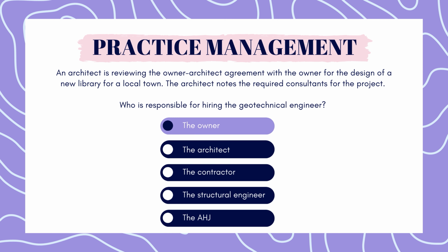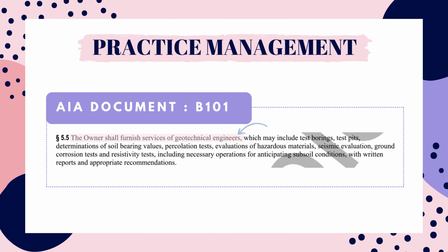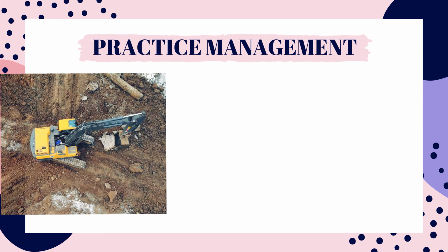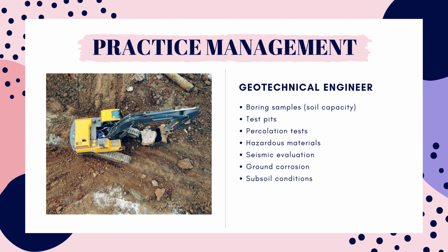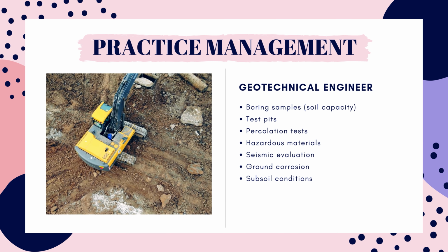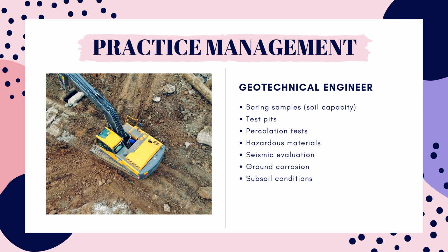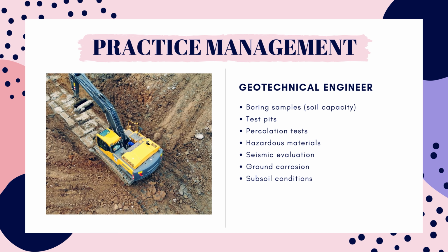The answer is owner. The geotechnical engineer is retained by the owner. This is stated in AIA document B101 under Owner Responsibilities, section 5.5. But what does a geotechnical engineer do? They go to the site to take boring samples that they analyze to provide us designers with the bearing capacity of the soil. They can also run percolation tests, look for hazardous materials, provide a seismic evaluation, and many other similar tests that tell us about the subsoil conditions.